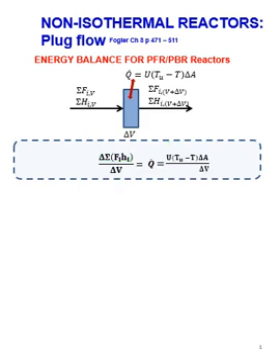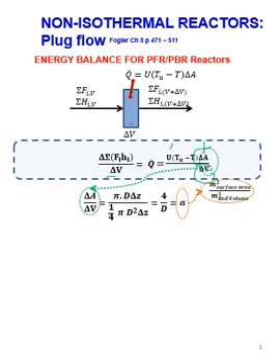And the heat transfer can still be calculated as a heat transfer coefficient multiplied by an area, and of course still divided by the volume of the slice. But now that area is the external surface area of that very small slice that we are considering. So for a tubular reactor, which is the shape of most reactors, we can write that by considering the external surface area, which is the circumference multiplied by the length that I'm considering here, divided by the volume of that small slice.